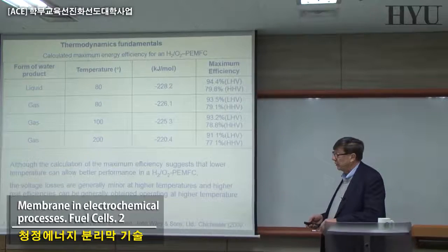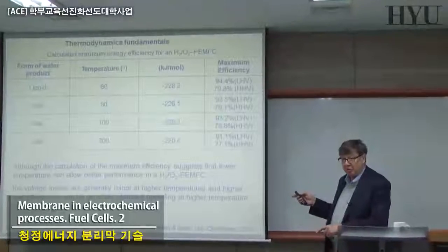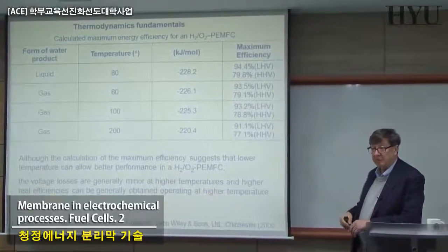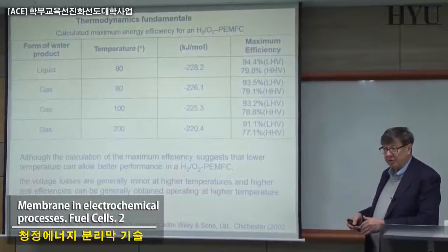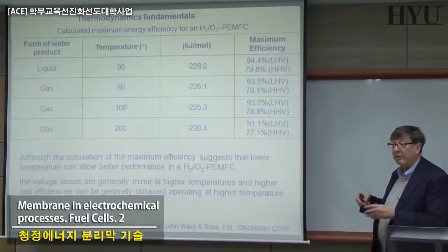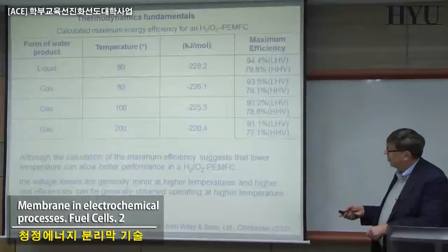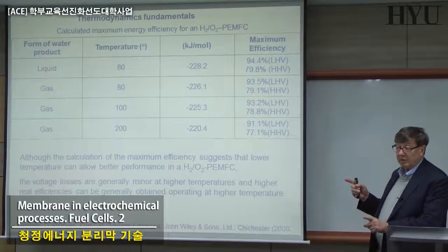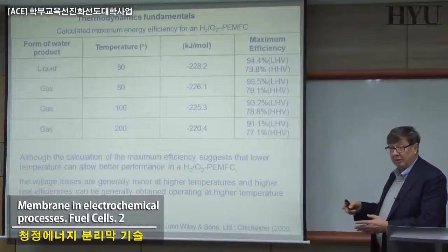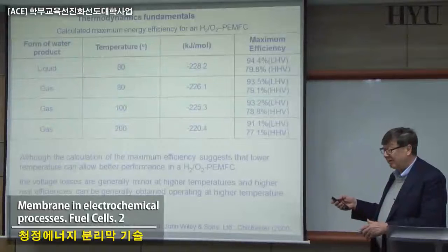In principle, you can help the situation by playing with the temperature. All the transport parameters, the diffusion coefficients, viscosity, etc., are functions of temperature. So if you want to increase, for example, diffusivity, meaning faster ions moving from the solution to the surface of the membrane, you can increase temperature. With increasing temperature, viscosity decreases. That is also a way to avoid too much of another resistance that you can have in the system.